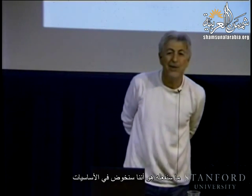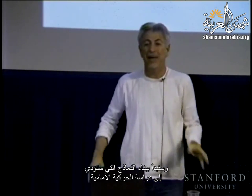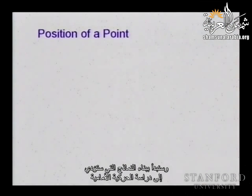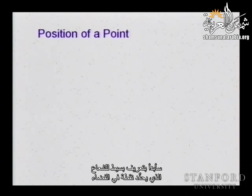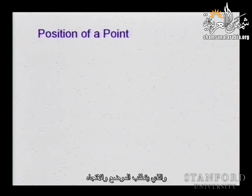What we're going to do, we're going to go to the basics now, and we're going to start by building the models that would lead to the forward kinematics. So I'm going to start with the simple definition of a vector that is defining a point in space, and we are going to go from there to building the models for representing an object in space, which requires position and orientation, and then we connect these objects.